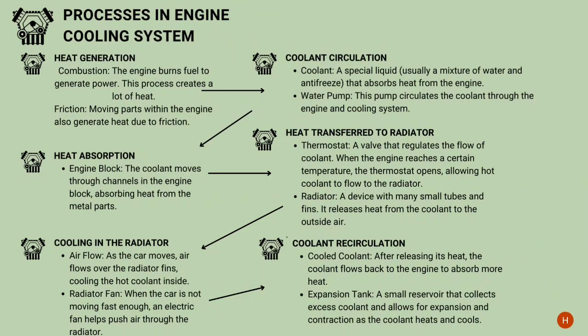In the combustion part, the engine burns fuel to generate power, and the process creates a lot of heat. And in the friction part, moving parts within the engine also generate heat due to friction. So the second one, coolant circulation, consists of coolant and the water pump. Coolant is a liquid made of a mixture of water and antifreeze that absorbs heat from the engine, and the water pump circulates the coolant through the engine and cooling system.